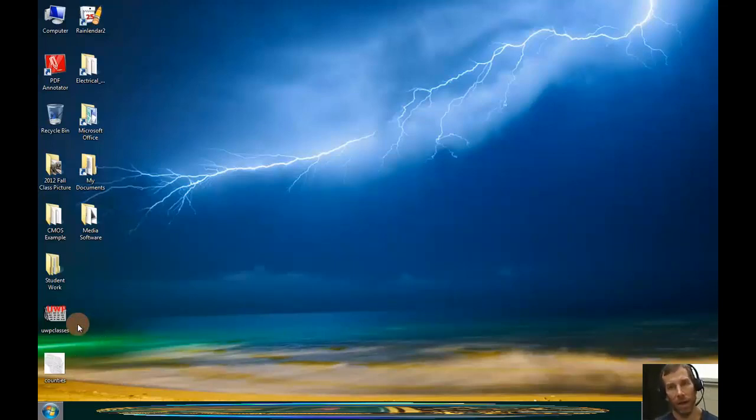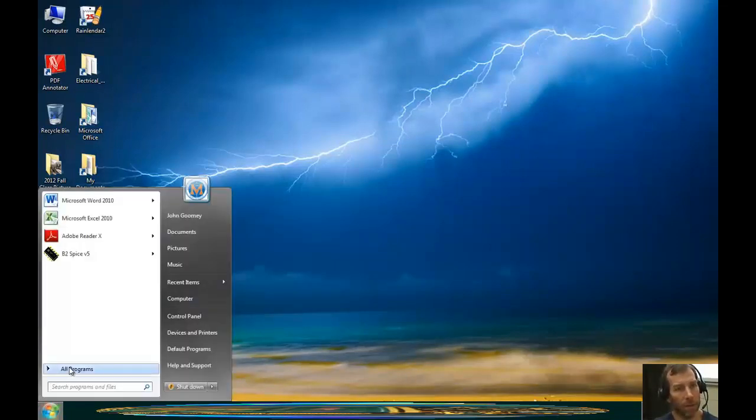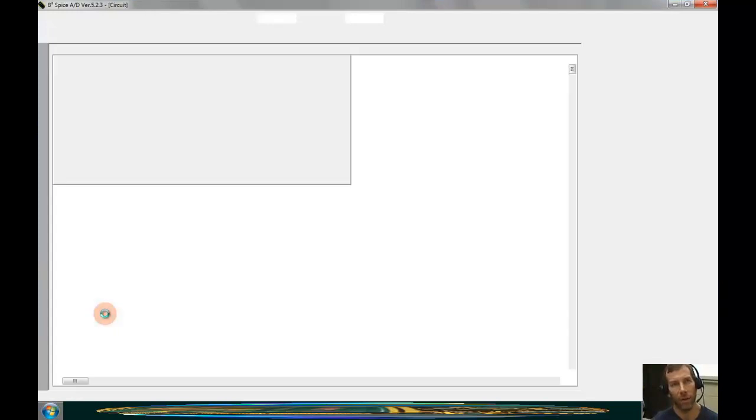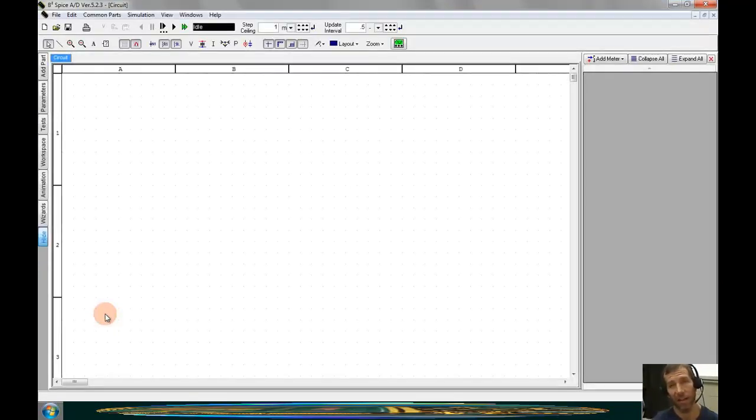The handout corresponding to this video can be found in D2L or on the instructor's webpage. To begin, we need to open B2 SPICE. This is done by going to the Start menu under All Programs and selecting B2 SPICE AD version 5. Under this menu item, click on B2 SPICE version 5. If you're at a streaming video location, you'll need to log into the VMware client in order to find this menu item. Once you've started the program, you'll see a grid.